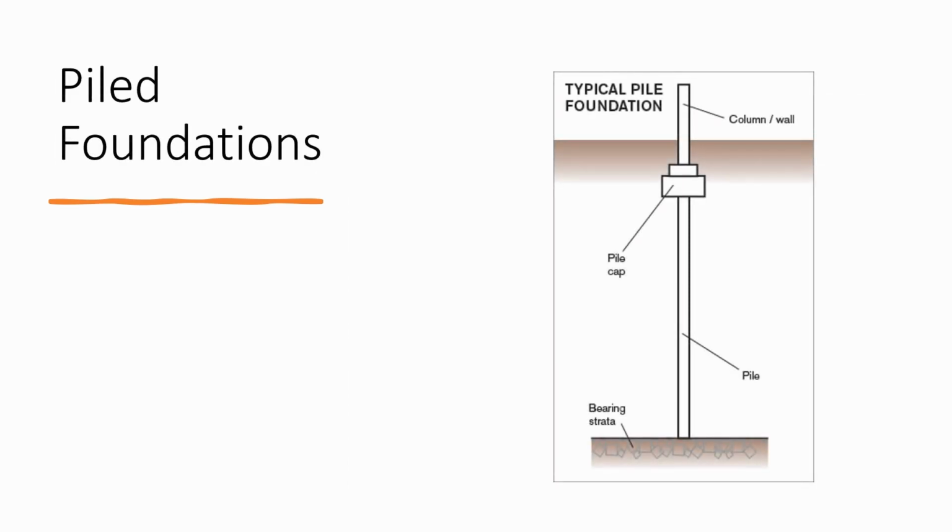We have the pile foundations, and these are deep foundations. They're formed by long, slender, columnar elements typically made from steel or reinforced concrete, or even sometimes timber. A foundation is described as a pile foundation when its depth is 3 times its breadth. Pile foundations are principally used to transfer the loads from superstructures through weak compressible strata or water onto stronger, more compact, less compressible and stiffer soil or rock at depth, increasing the effective size of the foundation and resisting horizontal loads.